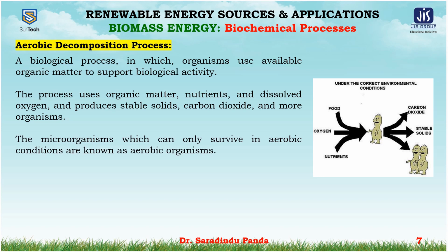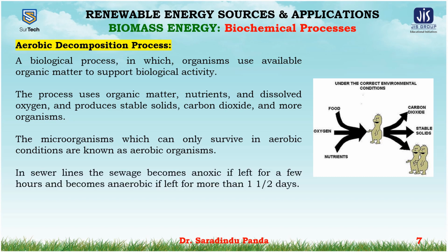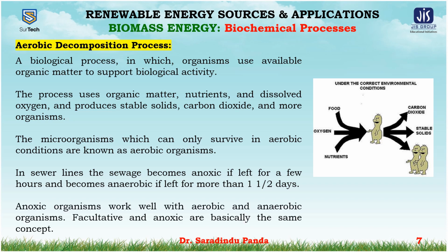The microorganisms which can only survive in aerobic conditions are known as aerobic organisms. In sewer lines, the sewage becomes anoxic if left for a few hours and becomes anaerobic if left for more than 1.5 days. Anoxic organisms work well with the aerobic and anaerobic organisms. The facultative and the anoxic are basically the same concept.